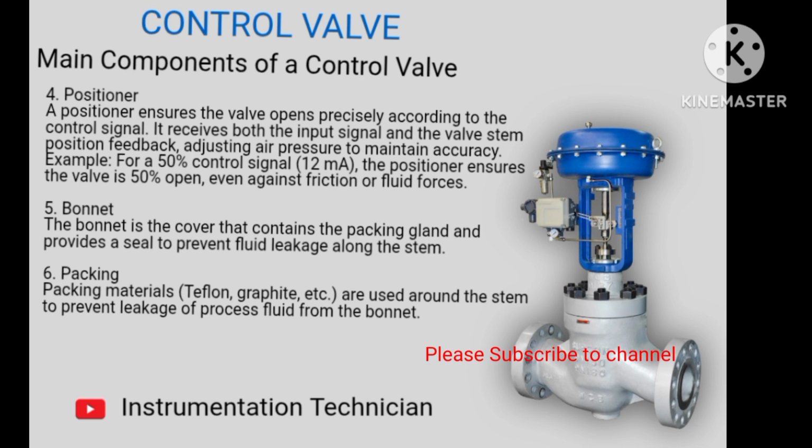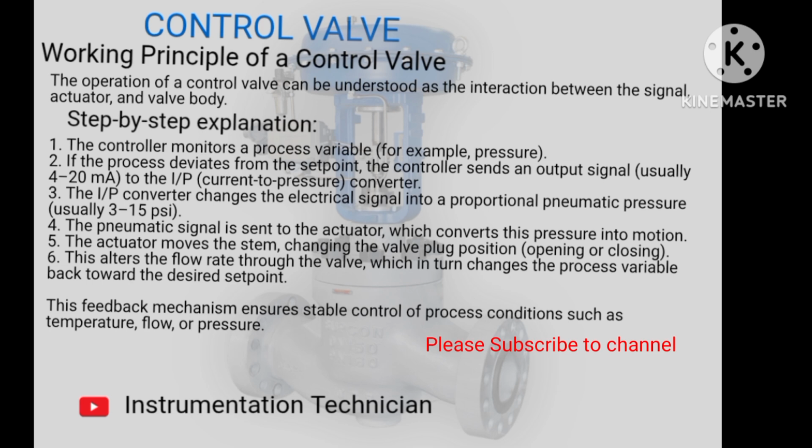5. Bonnet. The bonnet is the cover that contains the packing gland and provides a seal to prevent fluid leakage along the stem. 6. Packing. Packing materials, Teflon, graphite, etc., are used around the stem to prevent leakage of process fluid from the bonnet. Working principle of a control valve.